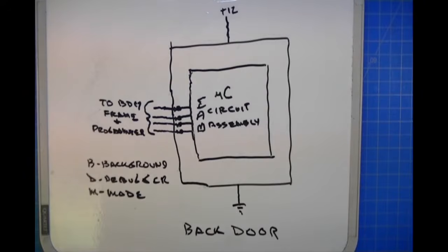As I said previously, if you have a failed flash update via the CAN bus, via the front door, something fails, and you are left with a brain damaged ECU because half of its data is not available, or is corrupt, and it won't work. Basically, as far as you're concerned, it's a throwaway module.